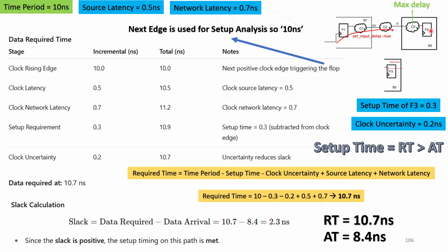So here is something which we are calculating: setup. The next edge is used for setup analysis, so it is 10 nanosecond. The first edge is at 0 nanosecond, the second edge is at 10 nanosecond. So setup will be calculated at this second edge.